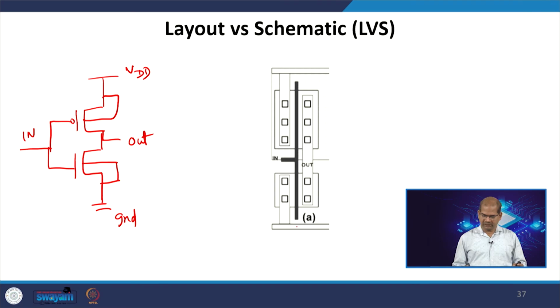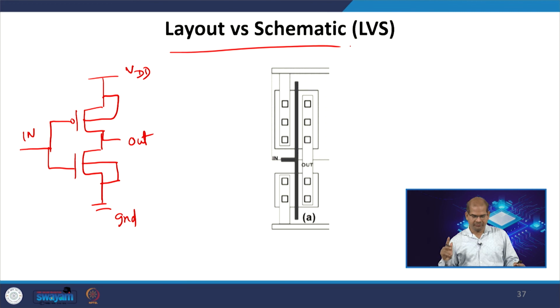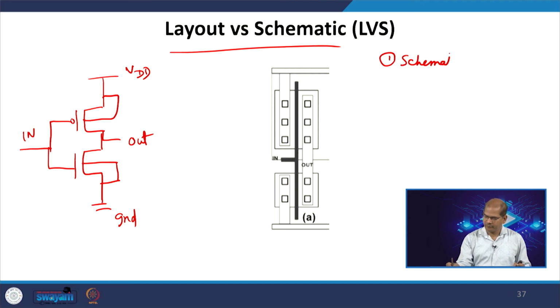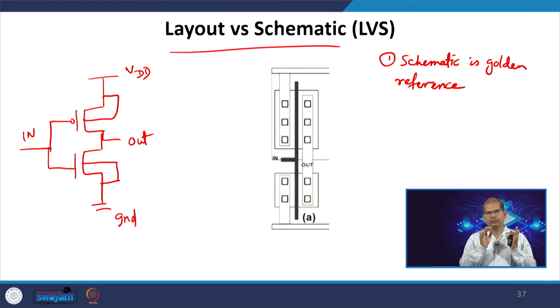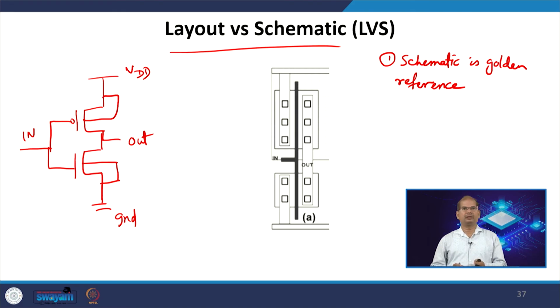But whenever you are thinking of layout versus schematic, a few things I need to point out here. Your schematic is a golden reference. It means that you are doing the schematic carefully, there is no mistake in the schematic, and you have simulated it. Then only can you compare it with the layout.